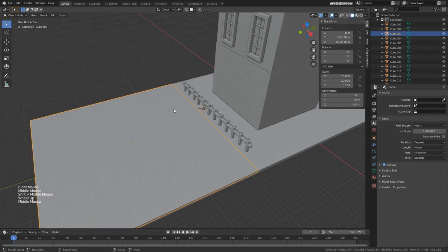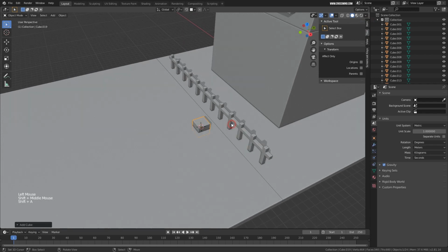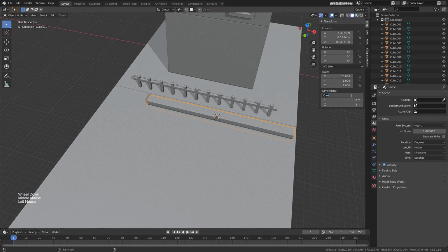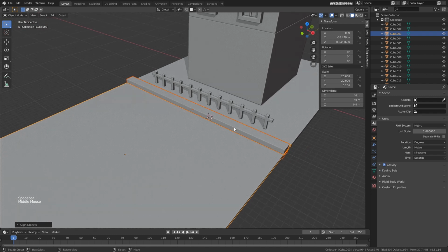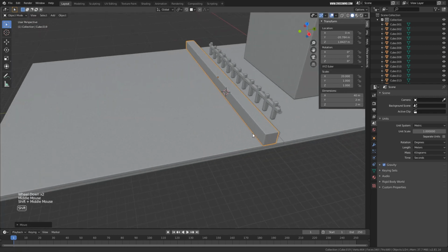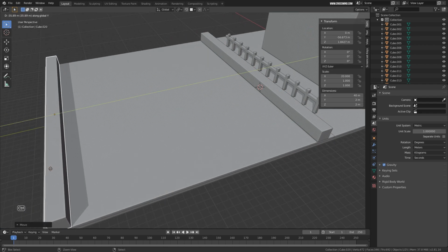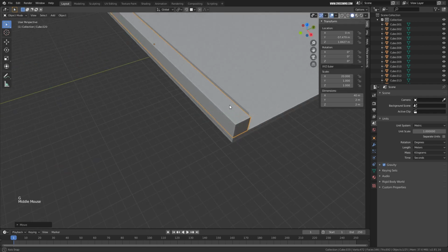Okay, so I'm going to make something like a roadside. Let's create a cube over here and just type 30 in the X direction. Okay, or 40, and I'll align these two. Hold down the control for snapping and Shift D, move it into Y and hold down the control key, G, Y and control for snapping.